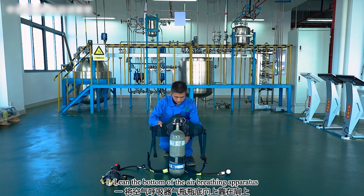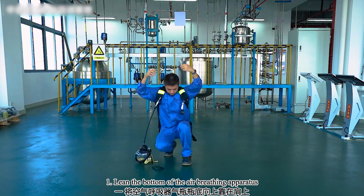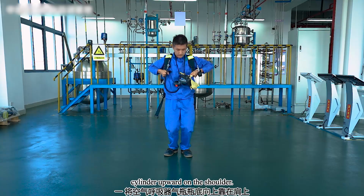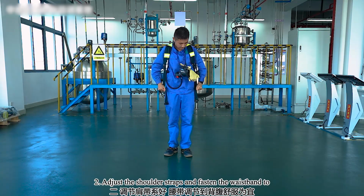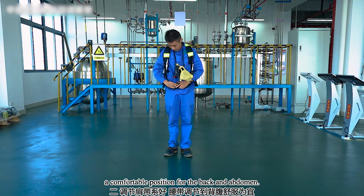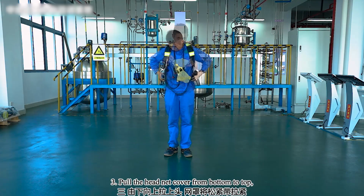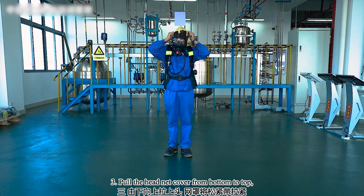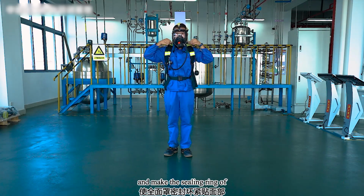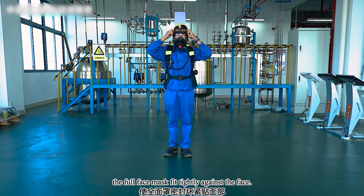Usage method. First, lean the bottom of the air breathing apparatus cylinder upward on the shoulder. Second, adjust the shoulder straps and fasten the waistband to a comfortable position for the back and abdomen. Third, pull the head net cover from bottom to top, tighten the elastic band, and make the ceiling ring of the full face mask fit tightly against the face.